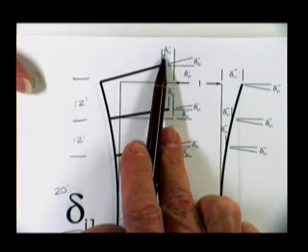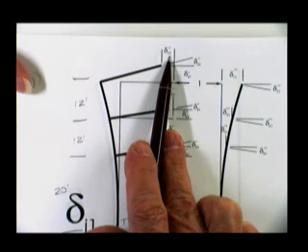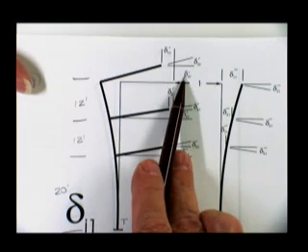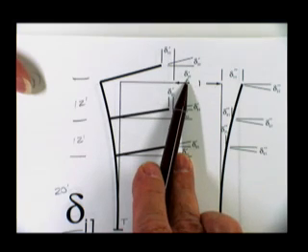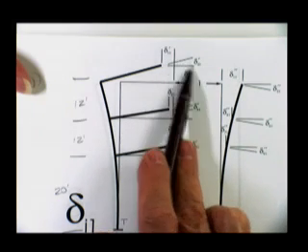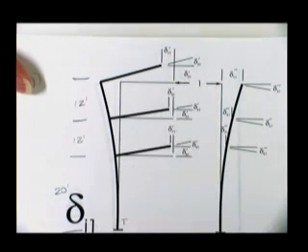His name is delta in the number 1 position because you put a unit load in the number 1 position. He moved up, deflection in the number 2 direction because of a unit load in the number 1 direction. And a rotation, a deflection in the number 3 direction, which is a rotational direction due to a unit load in the number 1 direction.